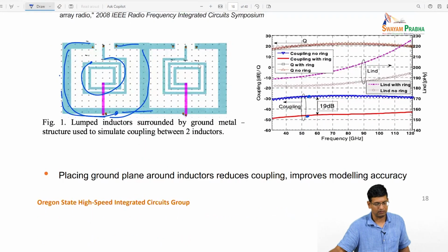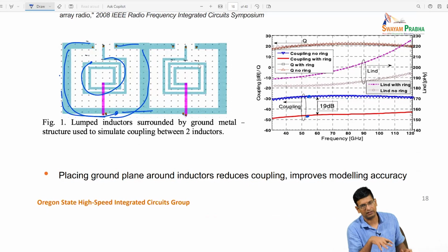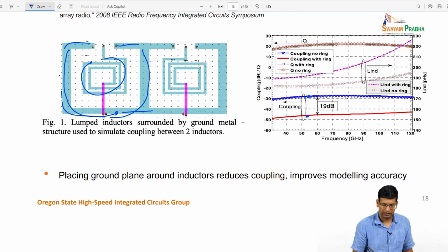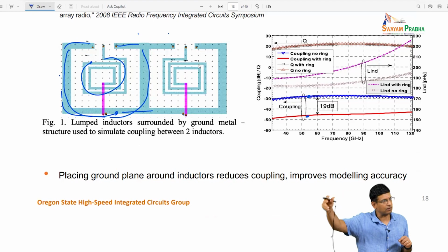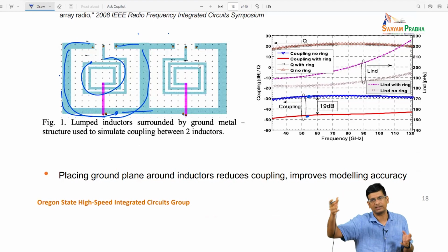So the usual thing that happens at millimeter wave is that the inductances are short, right, or small. So you don't have a lot of room, even if, for example, you want to physically space two inductors, the wiring to get to that longer space might itself be a significant fraction of the inductance that you want.